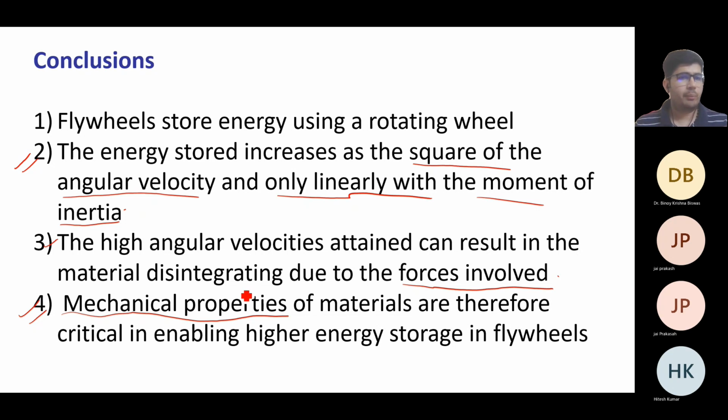Based on that, you have to select the proper material so that at the highest angular velocity, there will be no stress that can disintegrate the material of the flywheel. So mechanical properties of the material are critical in enabling higher energy storage in flywheel.